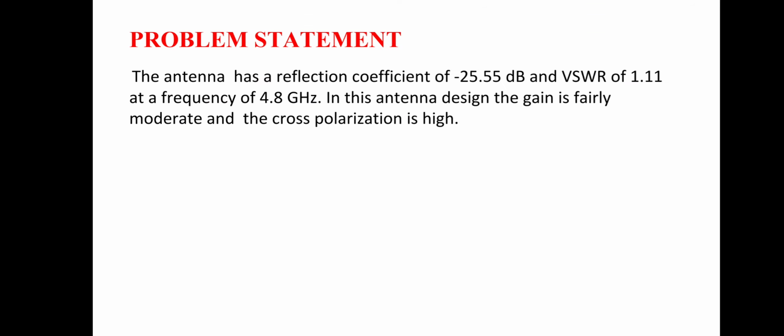It has many advantages, and the problem statement is that the antenna has a reflection coefficient of minus 25.55 dB and a VSWR, voltage standing wave ratio, of 1.11 at a frequency of 4.8 GHz. In this antenna, the gain is fairly moderate and the cross polarization is high.